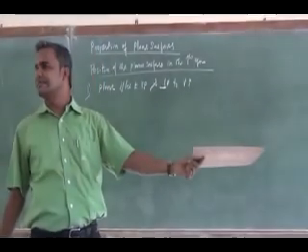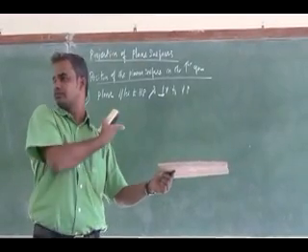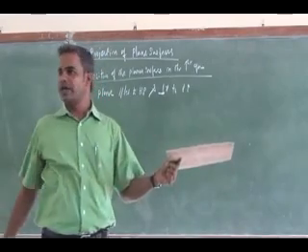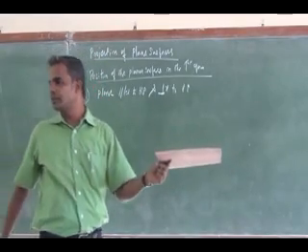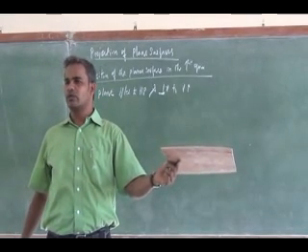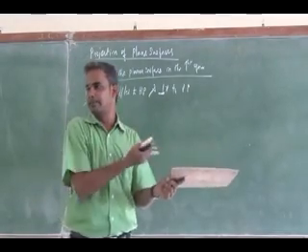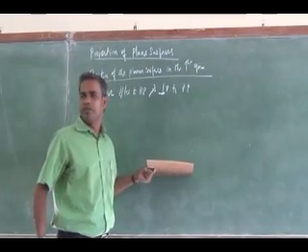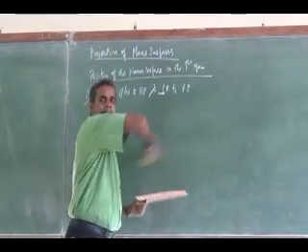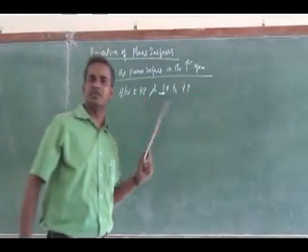Now this plane is parallel to HP, so I have to draw the true shape on HP, and the line will be seen on the front view. Why is it seen as a line in the front view? Since it is perpendicular to the reference plane, I can see a line as the view on the reference plane.